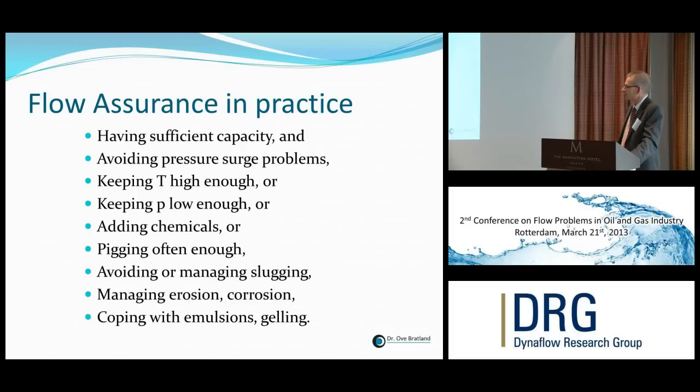And then it's about keeping the temperature high enough, maybe to avoid hydrates. That's one possible strategy. Or low pressures are also a good thing when we want to avoid those types of problems. Maybe we add chemicals, we add MEG or something in order to avoid hydrates building up. It could be we use pigging, as we saw here, as a strategy for getting out liquids that build up in our flow line, or to get out wax. Managing slugging or avoiding slugging altogether if we can, that can be a big part of our problems.